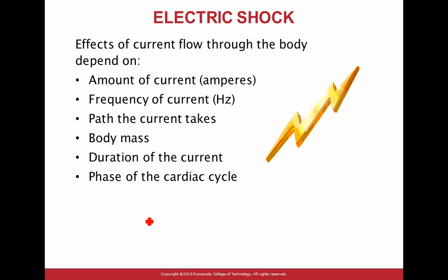Now, it doesn't matter if you're carrying a fully insulated plier like this one and you have a big ball of fire chasing you. It wouldn't do you any good, would it? Nothing. You're engulfed in a big ball of fire. So these are completely different. You could be standing in front of a panel, not touching anything, and the panel is open and you are within the limited approach or the arc flash boundary.